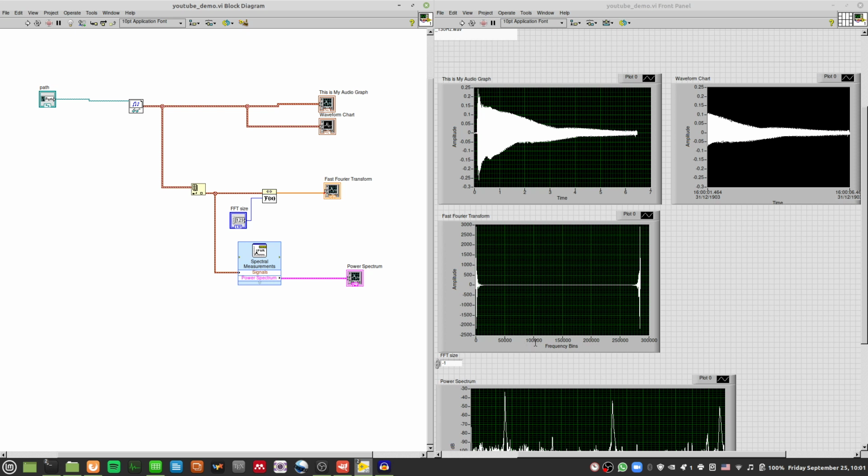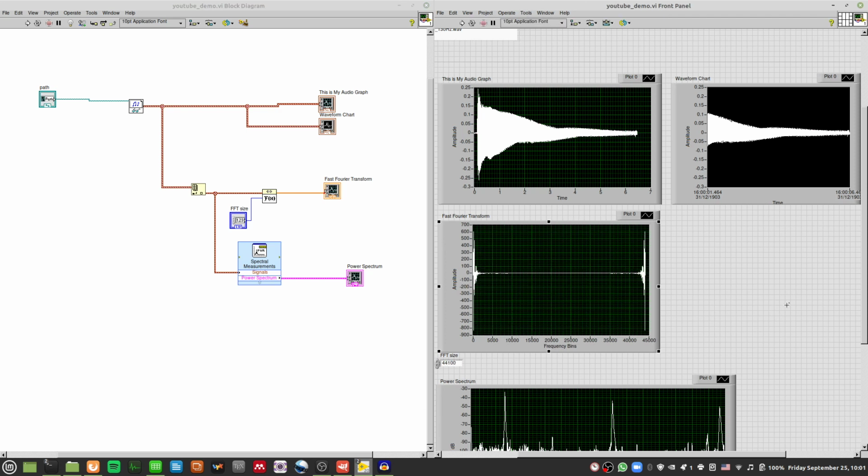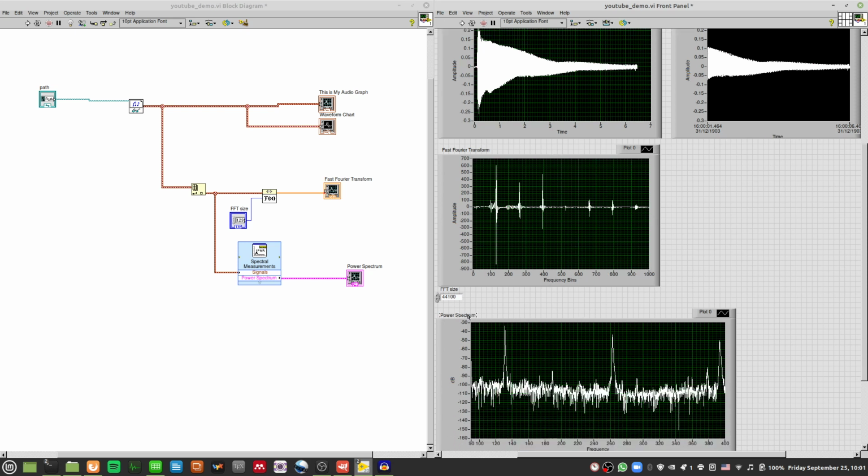All right, so how do you get the frequency bin to correspond to actual hertz? Now I want to give you something interesting. Now when I switch the FFT size to 44,100, this is a very special number, especially for audio files. Okay, so now we will have this fast Fourier transform, and I will actually switch it down to 1000 Hertz. Now notice where the peaks are. When I switch the FFT size to 44100, I'm only taking the first 44100 samples and performing a fast Fourier transform.